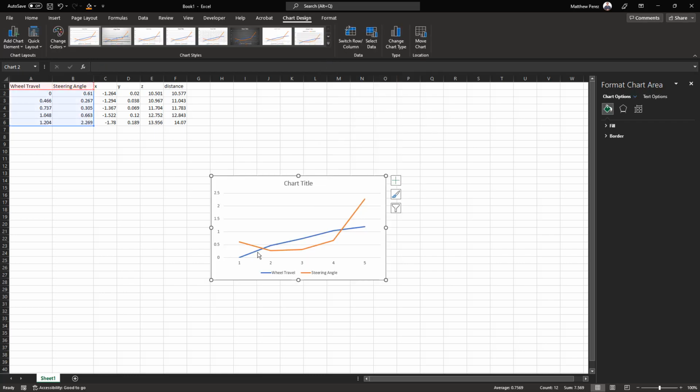So if I plot those, I can see as my travel increases that the angle is going from essentially a slightly toed out position. And that could be an overstable situation for something like a drift car, because obviously once you turn the suspension, it's going to change. If it's not really meant to go straight, that might be okay. But you can see that we're toeing in a little bit. And as soon as we get to this point in the travel, which was, again, once we got to about 3/4 of an inch, then it starts to begin to toe out again. And once we get all the way to, right here at about 1.25 inches is when things start to go really kind of wonky and they toed out drastically.